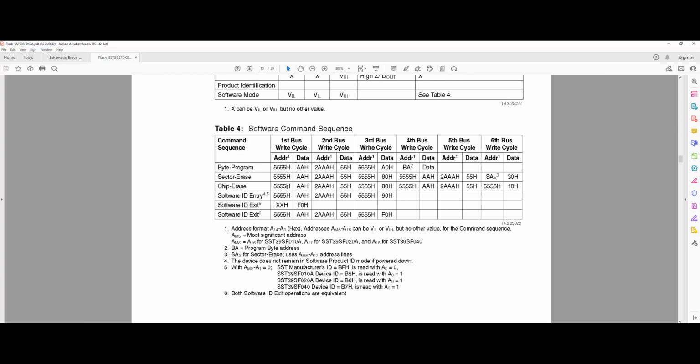And that's why probably later, if we really want to, let's say, save a file or a value into our flash memory, then we need to come up with a little bit of code. Basically, we need to develop probably a mini file system, let's say, to take care of these preparation steps before we write the data into our flash. And that has actually been done quite well by Carsten in his minimal project.